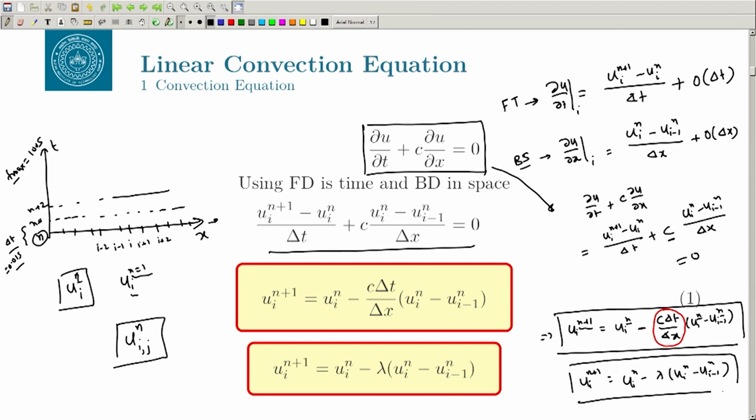And this number has very big significance in CFD. Regardless of what kind of problem you are solving, using the RANS approach, LES, DNS, whatever, you always need to take care of this number, which is the Courant number. It is also called the CFL number. Very crudely, let us see what it represents.